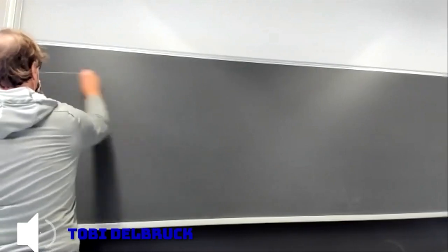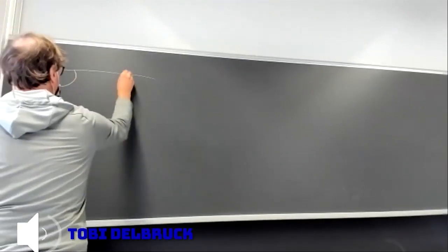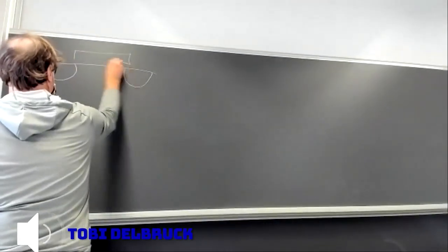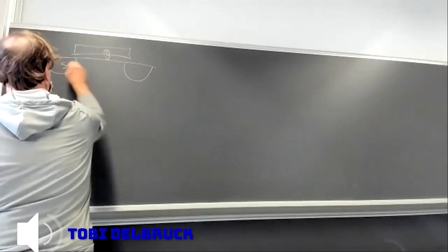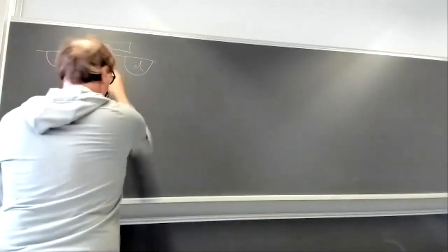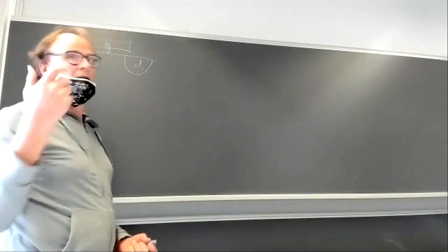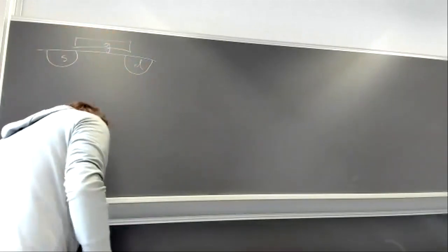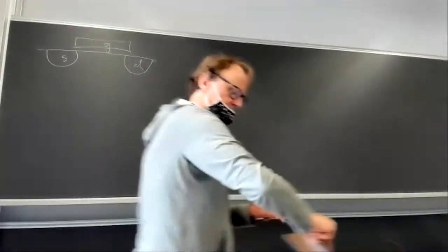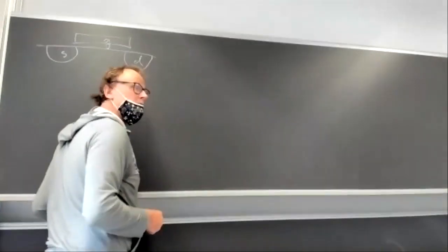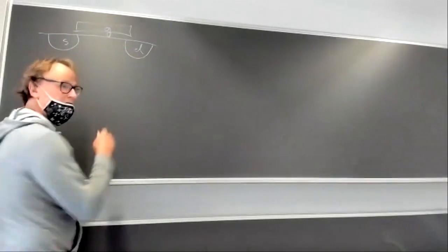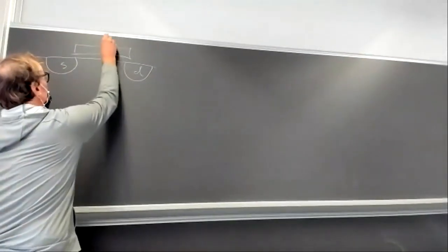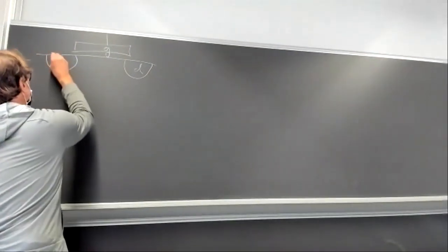Okay, so let's just draw the cross section of the transistor here. There's a source at one end, a drain at the other end. Above it is a gate. And the source is where the carriers come from, either electrons or holes, depending on the type of transistor. And the drain is where they fall out. So let's take the concrete case that is an N-type transistor.